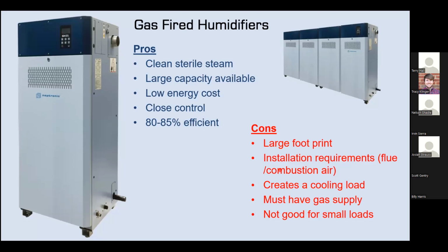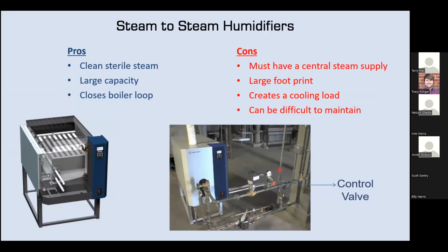And so there's a built-in redundancy here, without having to actually buy two sets of humidifiers, if you have a higher capacity. Steam to steam, if you do have a boiler, the benefit of steam to steam is that the boiler can be maintained with boiler chemicals. You're not going to put it into your air. You can put just tap water and make clean steam that goes into the air and humidifies that way.